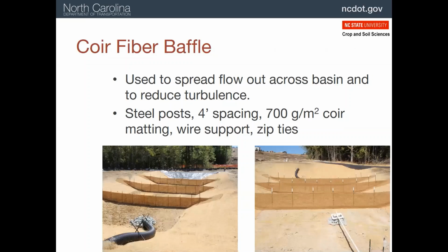All right, so we're finally going to get to those porous baffles. The purpose is to spread the flow across the whole basin, which will slow the water down. They also reduce turbulence or flow up and down and sideways. Both effects help settle sediment much better than an open basin. We'll discuss their installation on the next slide, but let's linger here because this skimmer basin has everything you need to remember about their installation.